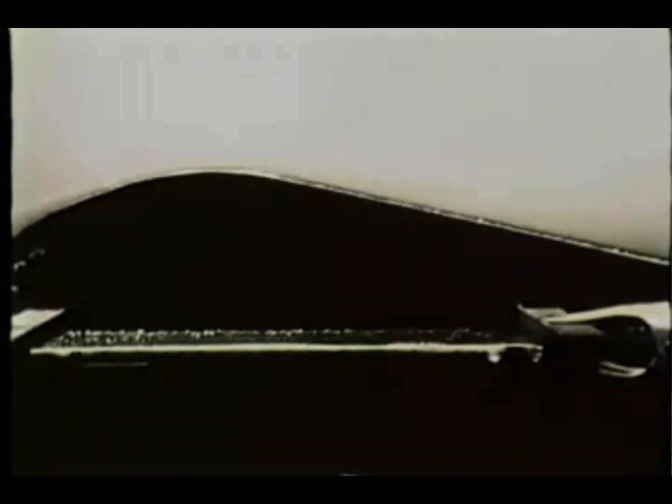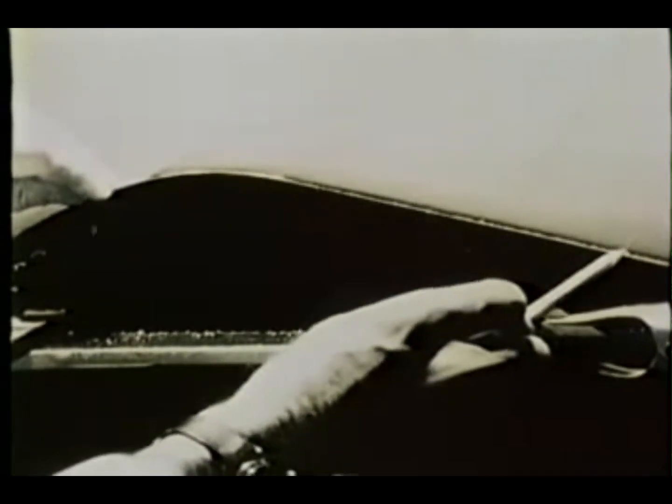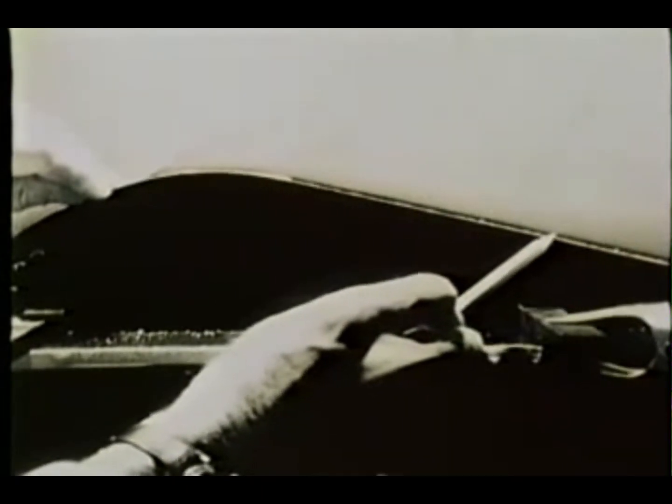This boundary layer around a channel bend is made turbulent by placing an obstruction in the layer upstream. The obstruction stimulates the naturally occurring processes and hastens the onset of transition. The flow here is all downstream. Removing the trip rod results in separation and backflow. Bubbles accumulate at the separation point.